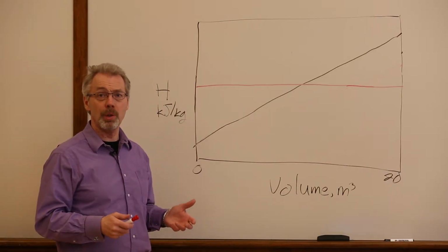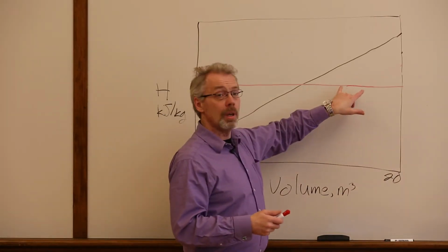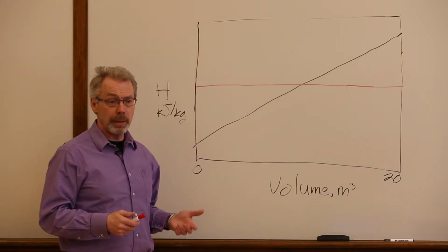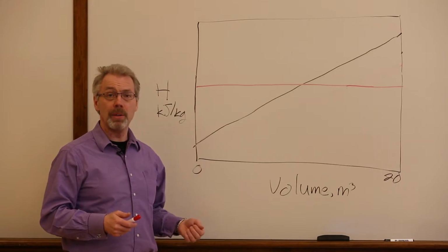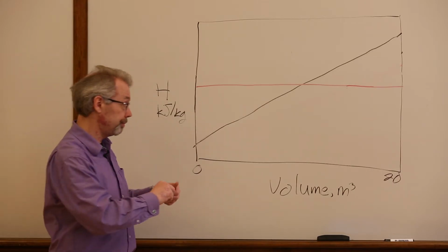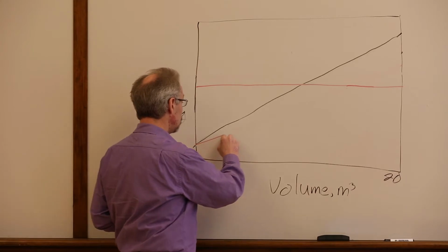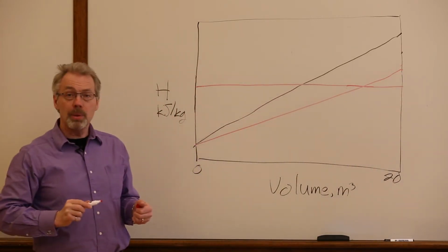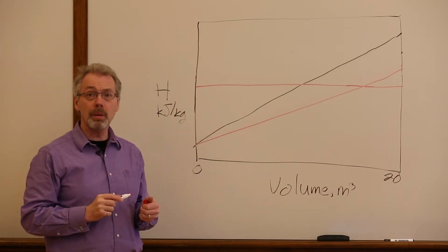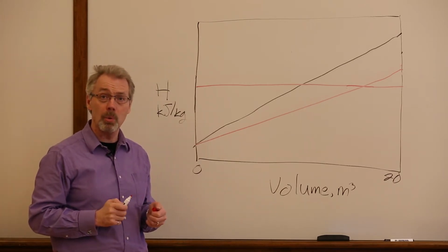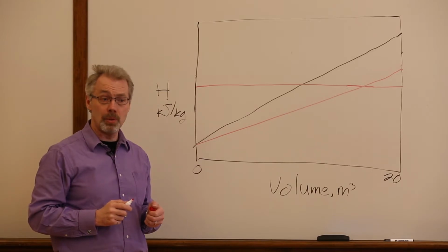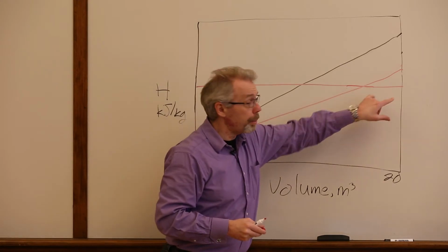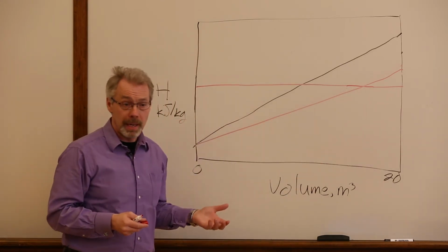Light-off displaces a large volume of water. In this case, about 10 cubic meters. Reducing the volume of water that is displaced during light-off will reduce the surge that taxes the capacity of the startup valve. We can reduce the volume of water by targeting a lower enthalpy or water or steam quality that exits the OTSG. Then the OTSG will displace, say, 2 or 3 cubic meters of water rather than 10.